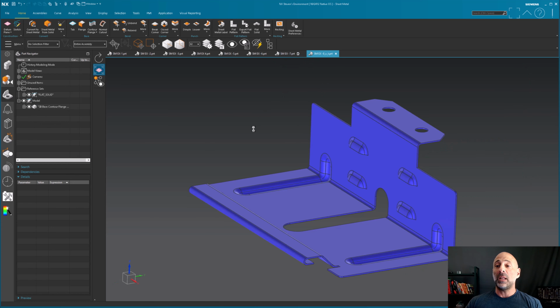And then for the final exercise, I get into designing this part from an imported sheet metal. It could be from whatever system. It is a Parasolid. And then I talk about laying out datums and the method to lay out datums, and then how to associate your various sheet metal functions to those datums to make sure that if something changes or updates, things move along with it. And setting up those datums in the context, almost sort of like working within the context of an assembly and the methods that go along with it.